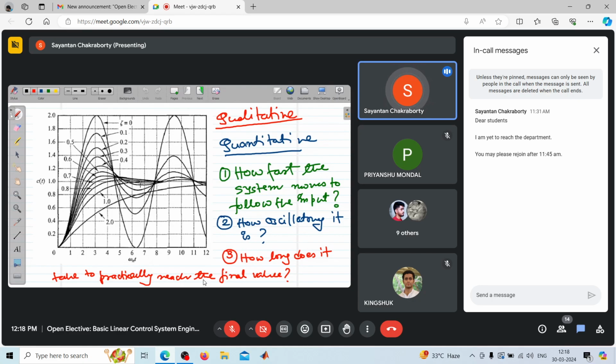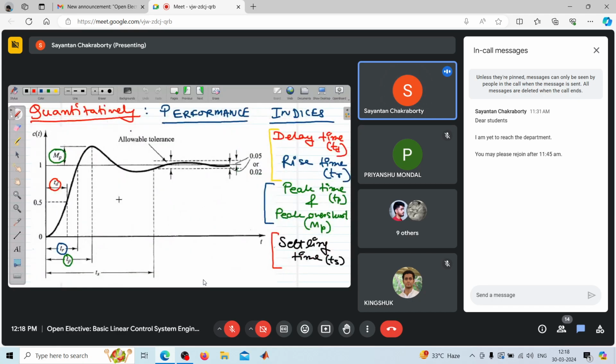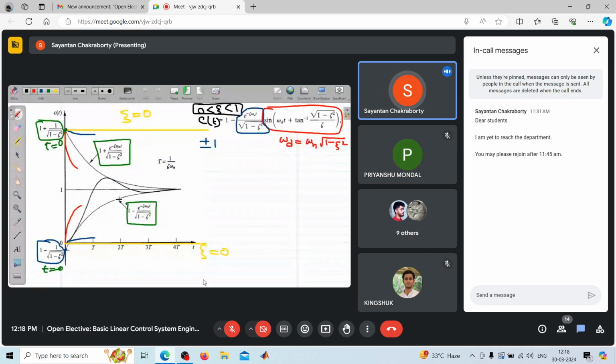Obviously, you will say that the overdamped response is the slowest. I agree. So this comes out of the equation. So the next two are critically damped and underdamped. Just ponder which one will be the fastest to reach the steady state. There are plenty of responses given over here. So I'll come to it later. This is one question that I'll ask, and I'll seek the answer later. So this is how the envelope determines the nature of the oscillation, or the peaks of the oscillations.